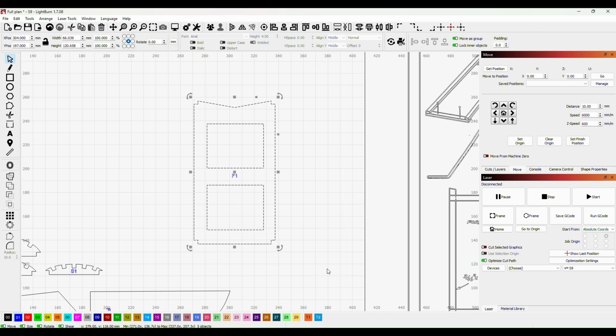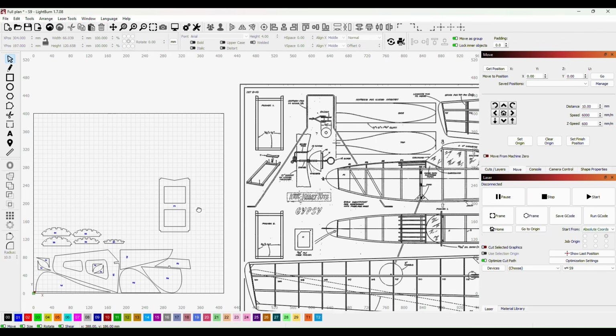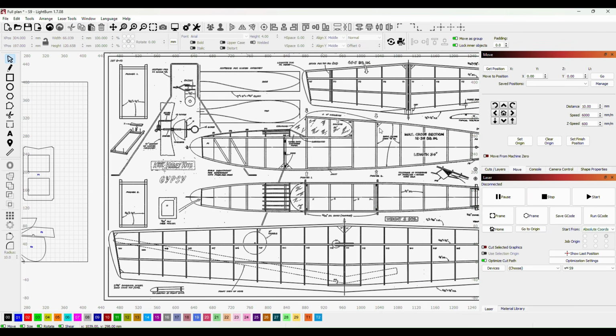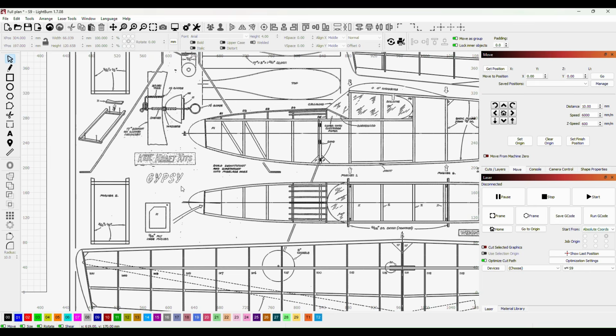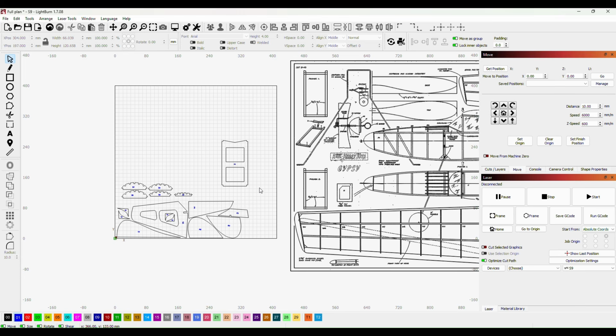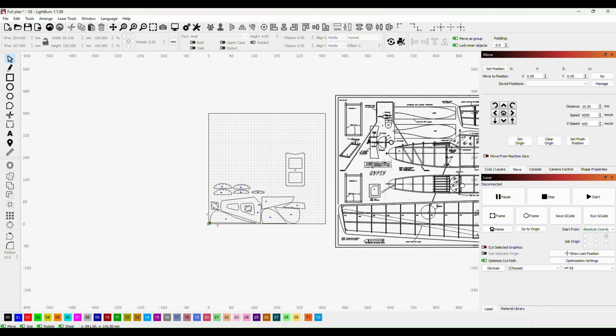And then group, and that's former F1 made. Former F2 will be very, very similar. It'll be a little bit shorter in height, but I'm going to do it in exactly the same way. And then what I'll do is I'll organise these onto a sheet, and we'll cut those all out of 1/8 balsa wood. So that's more or less it then for the fuselage.